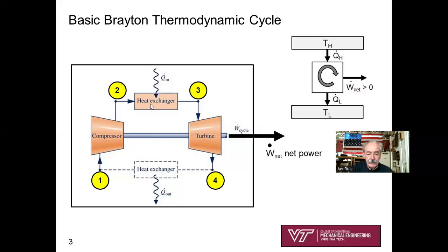Let's see, also remember that in the world, we combine fuel and air to provide the high temperature feed to the turbine. In our Brayton cycle model, what we're doing is modeling that combustion process as high temperature heat addition. The other thing to remember is you could basically bundle up this set of steady state, steady flow processes and jam them into this black box, the system operating in a cycle at a steady rate to visualize what's going on. Here's the rate at which you're adding heat, and here's what you're seeking to do, W.net. You're seeking to produce net power in some way or another.